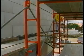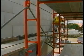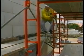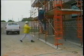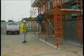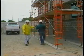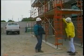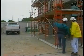It is the responsibility of every worker to look over the scaffold before you use it to make sure you're not getting onto something that is unsafe. There must also be a safe means of access to scaffold platforms. The ladder may be built into the scaffold, or a properly secured portable ladder may be used. No one is allowed to climb the cross braces.